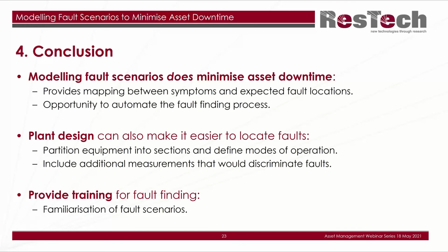Also, whilst designing plant, you can actually make it easier to locate faults. What we saw is that knowing the mode operation does isolate the fault location. So if you can design plant where there are actually maybe more switching devices than you would normally put, not necessarily going overboard, but if it can be designed in such a way where you can have devices that segregate the equipment, the plant, that would actually be quite good.